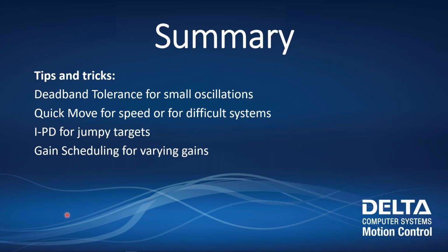See, one question came in: would it be better to use gain scheduling for heavy loads with short moves or just use quick moves? You know, I'm not sure I can answer that just right off the bat. You probably actually have to run the system and see which one would work better. But you are entirely correct. We have gain scheduling here to deal with some issues, but a quick move can equally well deal with that issue because now you're not tuning most of the motion. So you certainly can use multiple ways to solve a problem.